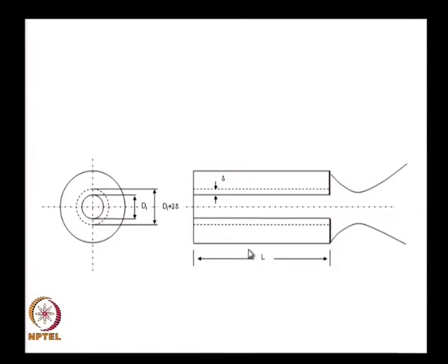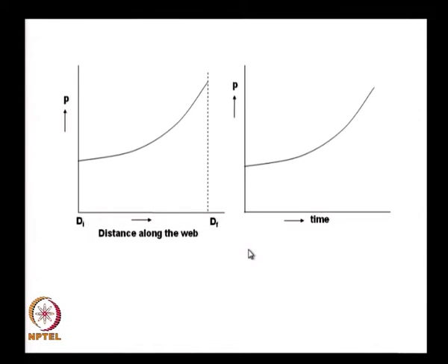I will take a look at it again today. If I say this is the inner diameter and this is the outer diameter, the pressure keeps increasing, and therefore as distance along the grain increases, the time increases. Therefore, I was able to plot pressure as a function of time, and we find that the thrust of this grain, thrust going as Cf into P into At, keeps increasing with time as shown here. Therefore, this is a progressive burning grain. This is what we did in the last class.